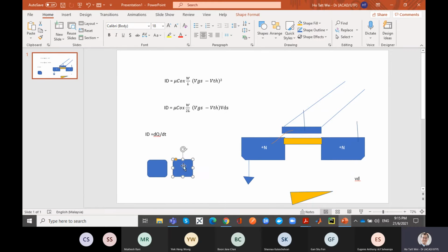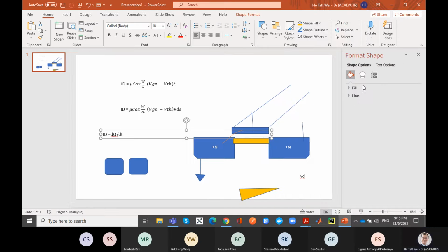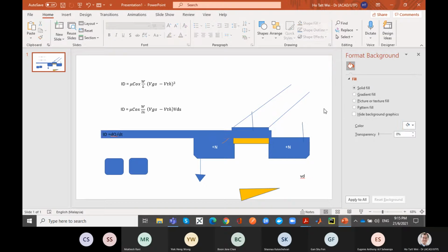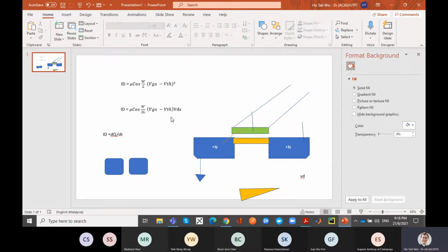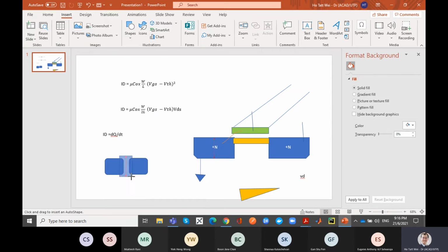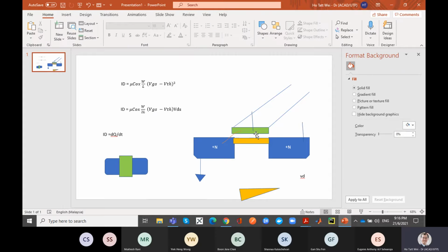This is your well. And then you literally have, okay, let me color this gate a different color, so at least we can visualize it. Let me color it green, for instance. It's not that it's green, just so you can visualize. If you look from the top, it actually looks like this. Okay, this transistor, if I look from the top here, it actually looks like this, where this dimension is the length and this dimension is the width.